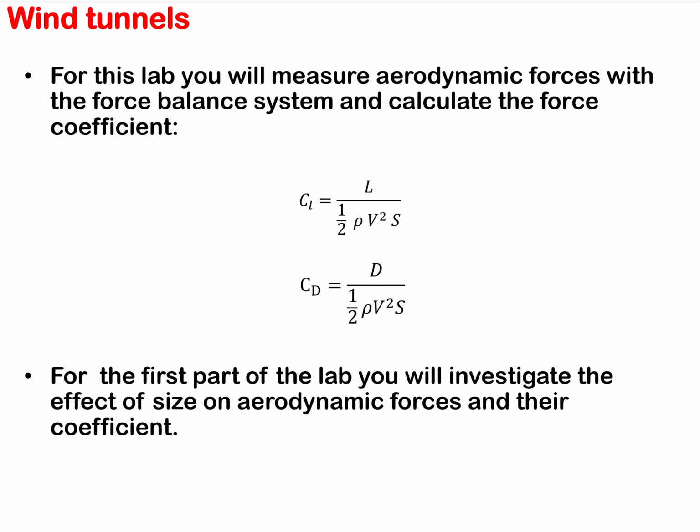You're given two different spheres. It's the same material, same everything, and then you have to calculate the drag coefficient for them. You have to compare the value of drag coefficient. The idea is drag coefficient for these two spheres must be the same, because the only thing that is different between the two is going to be their size. Everything else is the same.